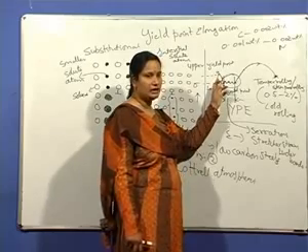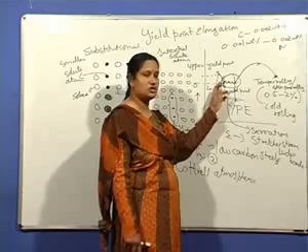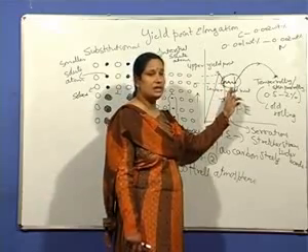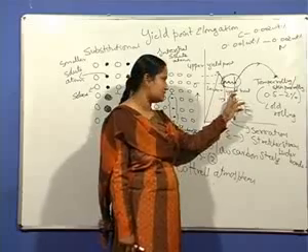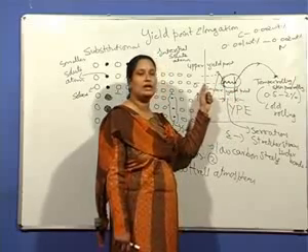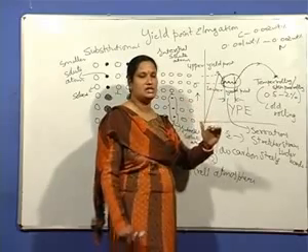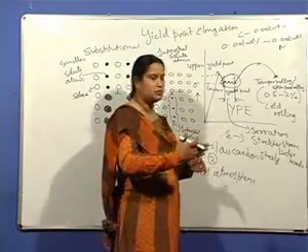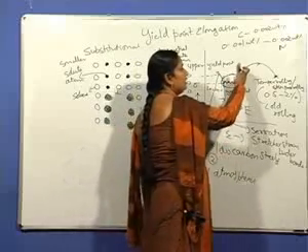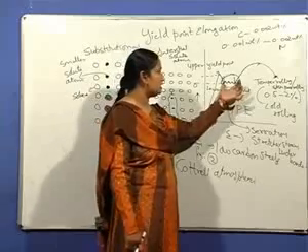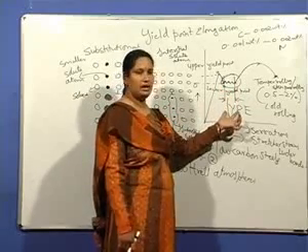The material undergoes yielding suddenly at point A, and stress drops. At point B, the material undergoes yielding at constant stress, known as the lower yield point. Once the dislocations are completely torn away from the atmospheres, the curve follows the normal path. This region is known as yield point elongation.